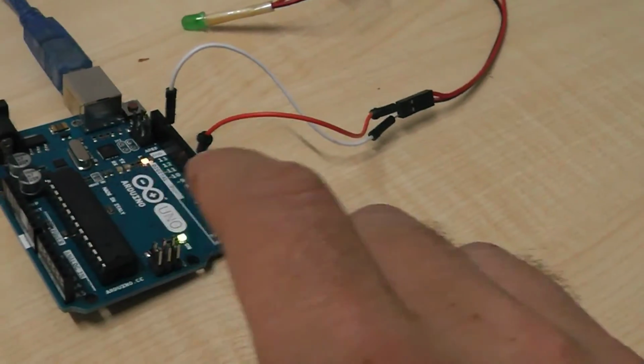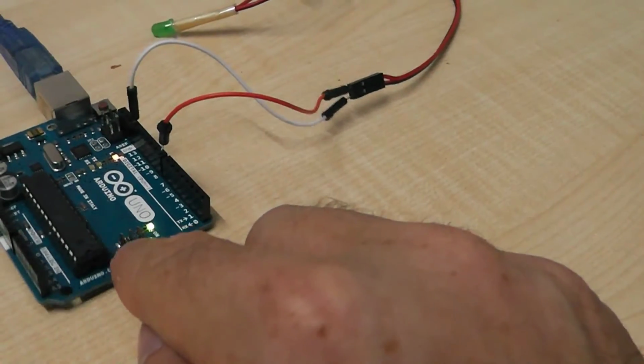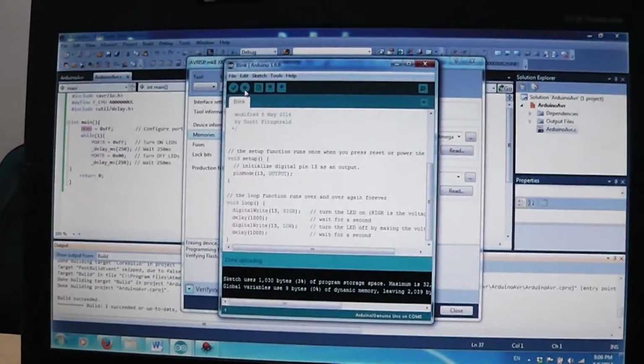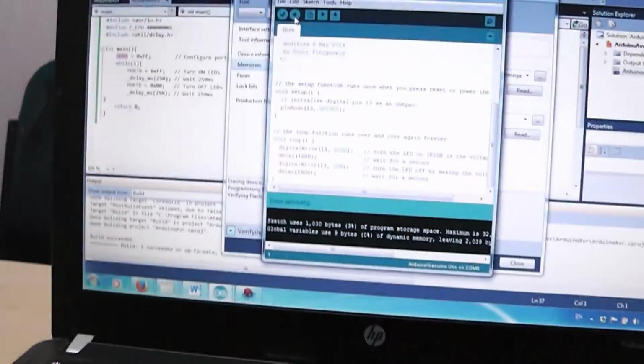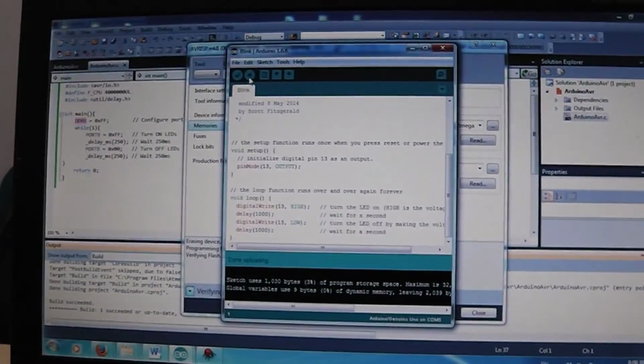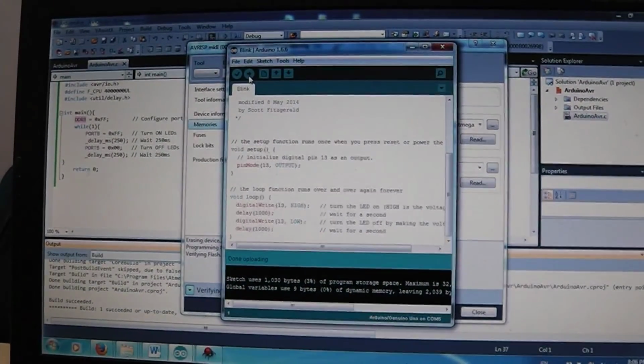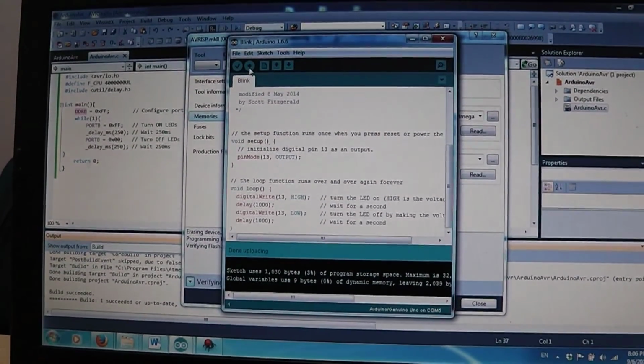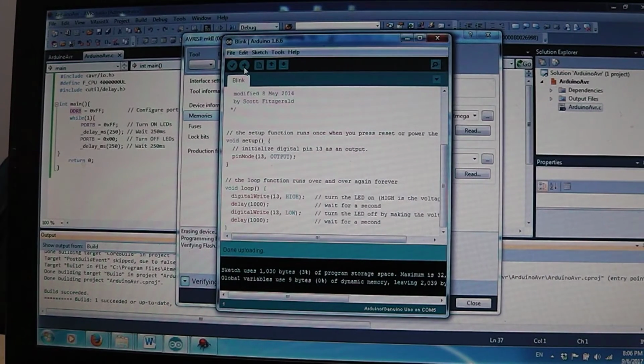To do so, you need to connect this board through the ISP to the programmer and the programmer to the computer. Then you can use Avr Studio to upload your programs. One important thing, if you want to use Arduino software, you should make sure that Arduino hardware Atmega 328P already has the bootloader, which is to communicate between Arduino software and Arduino board.